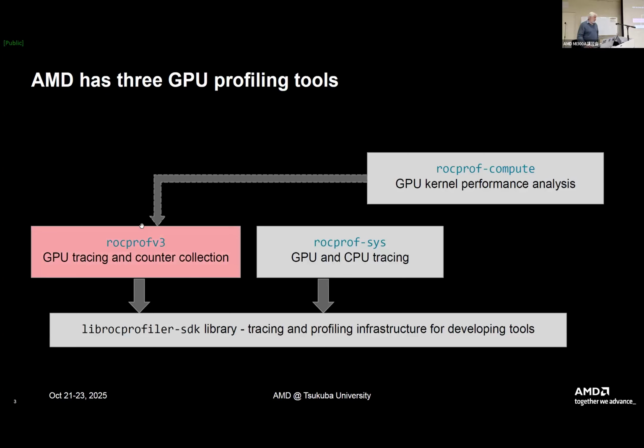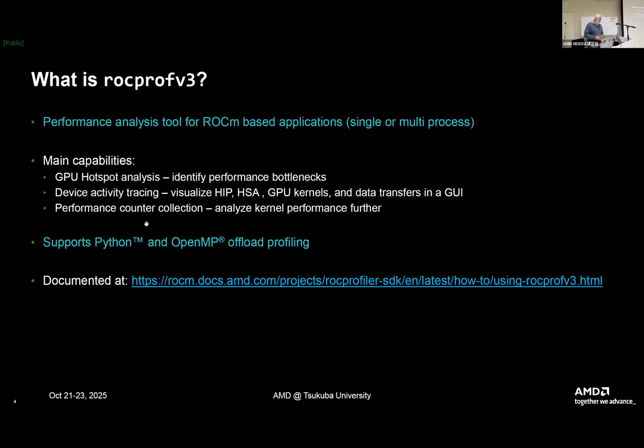We're going to talk about Rocprofv3 right now. And this is very quick to use because it's a command line tool primarily. And it will give you the key information generally that you need to understand what's going on. So it's going to show you the top few kernels that are taking up runtime. It's only looking at the GPU.